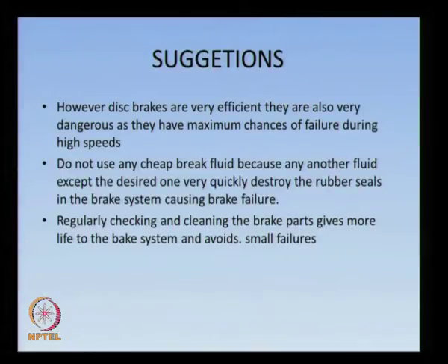However, the disc brakes are very efficient. They are also dangerous as they have the maximum chances of failure during high speeds. So never use any cheap brake fluid because of the chance of failure. Regular checking and maintaining of the brake pads gives more life to the brake system and increases the efficiency.